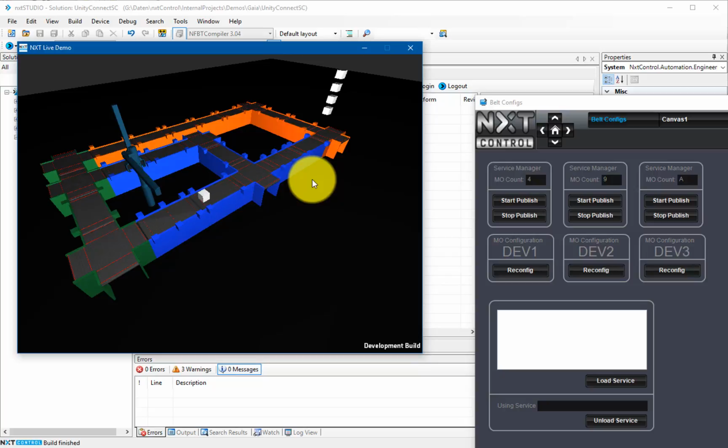As each controller works independently, objects will stop at the edge of a controller's environment. In our example, the controller domains are illustrated by different colors. If we put additional objects onto the conveyor line, the belts get controlled by the program logic, but prevent collisions of the items on the belts.